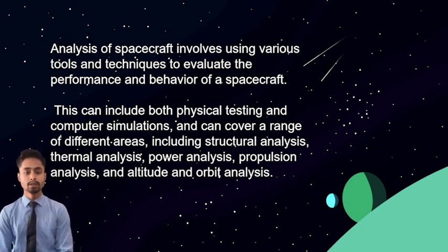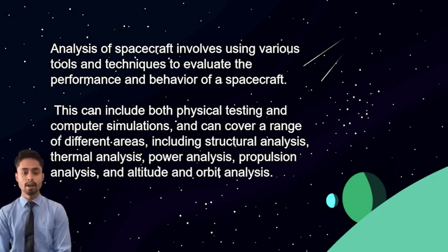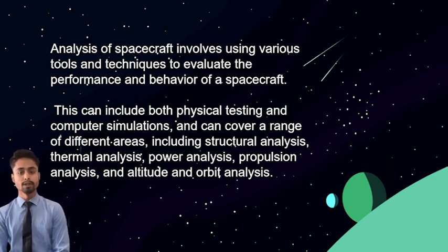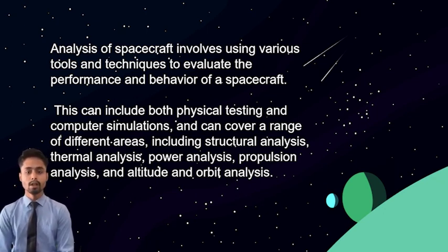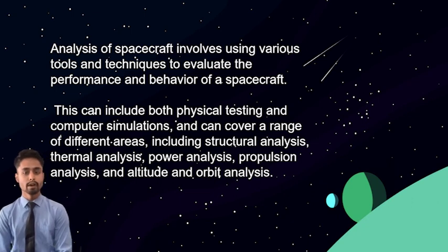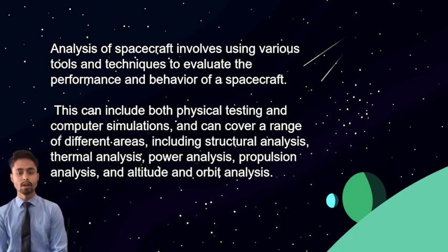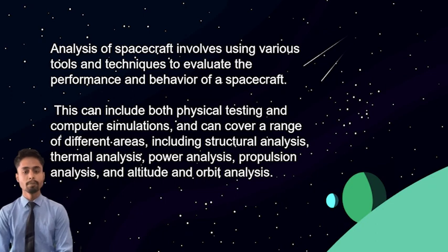Second, thermal analysis. Thermal analysis is used to evaluate the thermal behavior of the spacecraft and its components and to ensure that they can operate within their temperature limits. This involves using thermal modeling software to simulate the heat transfer and temperature distribution within the spacecraft under various conditions, including solar radiation, internal heat generation, and heat dissipation.